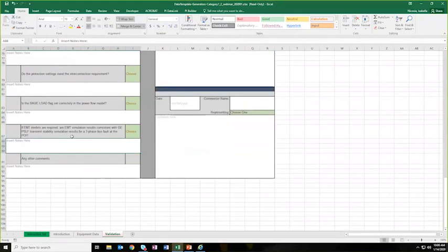Yeah, so base load 0 means the megawatt can be adjusted both upward and downward in the post-transient generation load balance change. 1 means it's blocked from upward regulation, and if it's 2, then it's blocked in both directions.